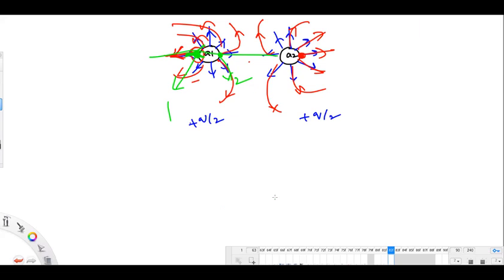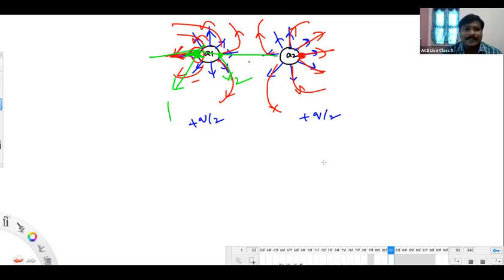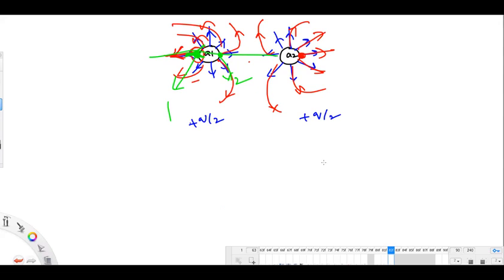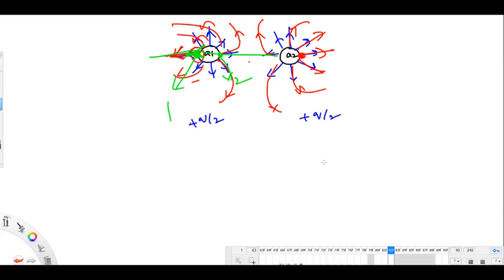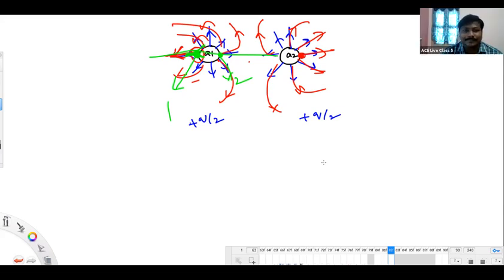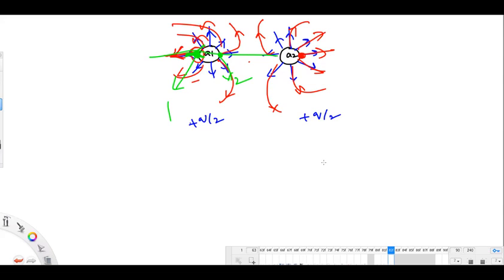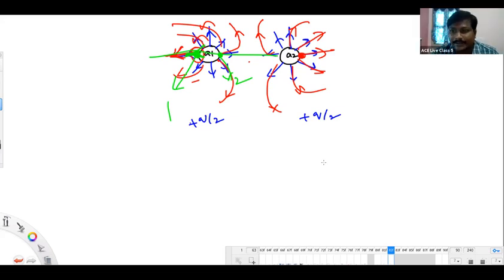How will corona impact radio interference, sir? Corona discharge is a high frequency discharge. Sir, how can you say it has a high frequency? The actual operating voltage is at 50 hertz. It is delivering light as well as sound, no? Yes, sir. Light is a very high frequency discharge, right? Yes, sir. The glow and the radiation you are getting there are of high frequency. That high frequency discharge might disturb the communication signal.